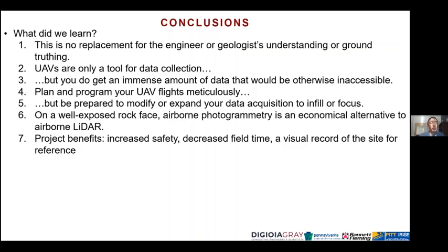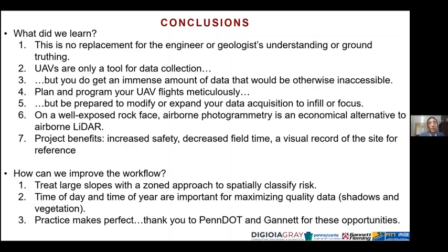Some of the benefits include drastically increased safety, decreased field time, and a visual record of the site for reference in the future. And how can we improve the workflow? You can treat large slopes with a zoned approach to spatially classify risk. Your time of day and time of year are important for maximizing quality data to reduce shadows and vegetation cover. And also, practice makes perfect.